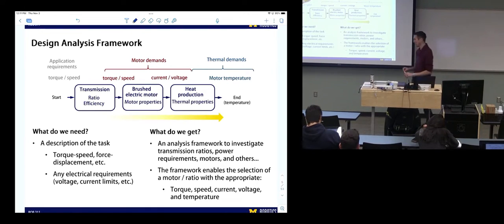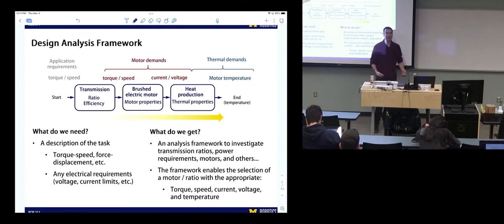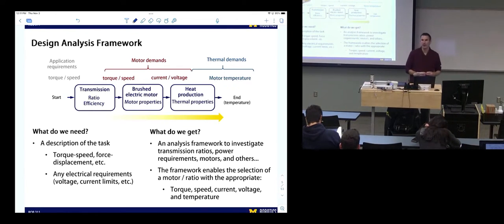So you're going to have constraints around temperature, but also around the driver. Anybody know what our drivers can take? There's two ratings that would typically be provided, a peak rating and a continuous rating. Peak would be defined for some short time interval. Continuous is forever. I think I can do like 2 amps continuous or something like that. So as long as we're under that, we're okay for our drivers.